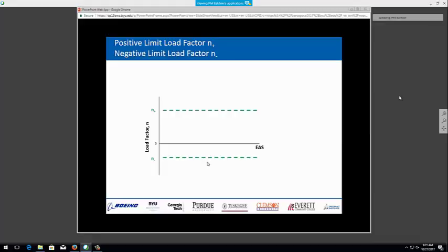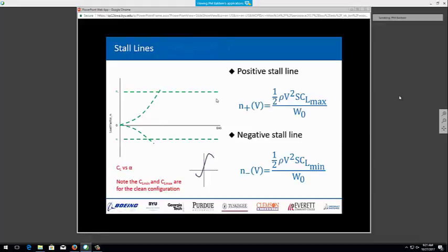I mean, you start talking Global Hawk, with a huge flexible wing that's got to get up through a lot of turbulent atmosphere. Once it gets to heights of 60 or 70,000 feet, it's not a problem, although there could be some clear air turbulence up there. So this is what we're talking about. You've got to fly your airplane within this load.